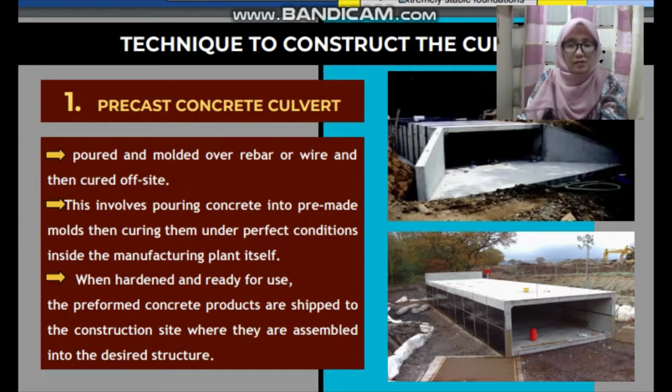And then we can see through rainfall patterns, because in situ concrete culvert should be installed during season of low rainfall in order to reduce the risk of damage and erosion during construction. And finally, maybe we can see for the pipe culverts.